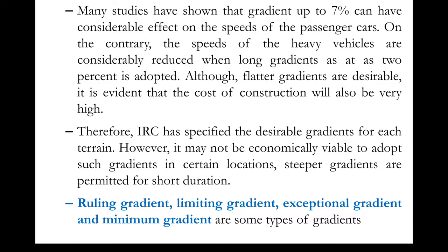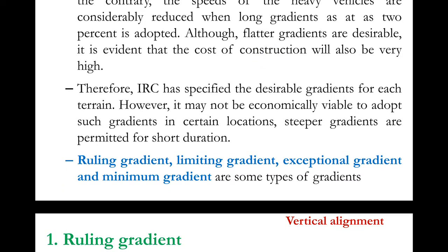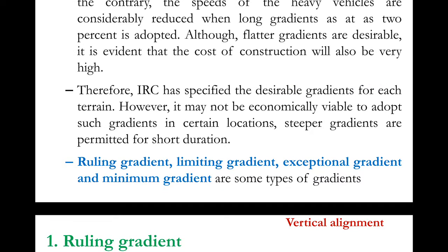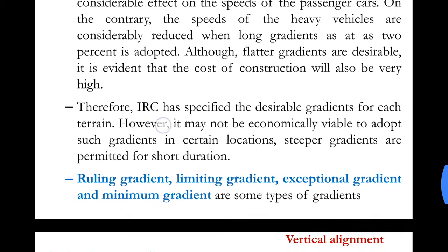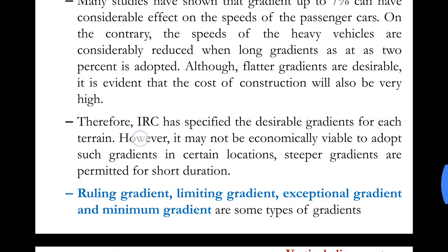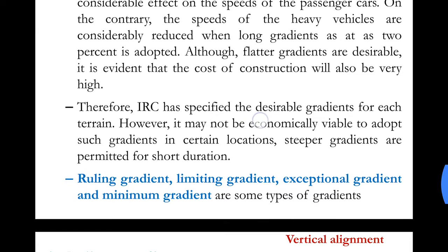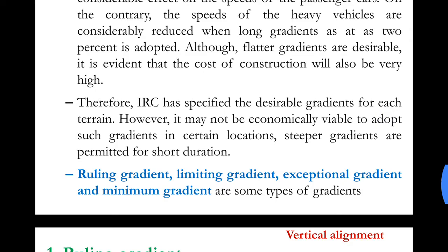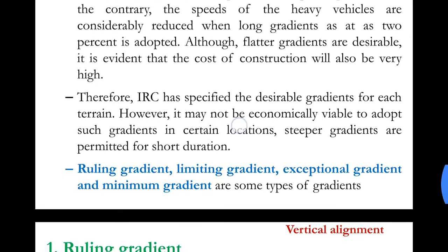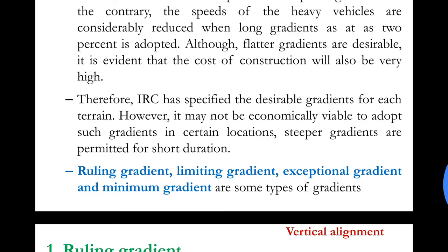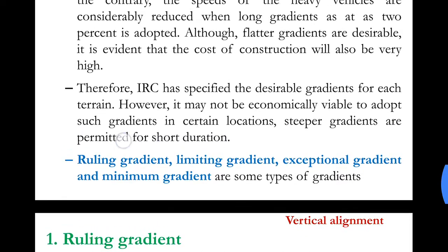Therefore IRC has specified desirable gradients for each terrain. For each type of terrain we have given a set of gradients. Out of these gradients we select whichever is suitable for that type of terrain. However, it might not be economically viable to adopt such gradients in certain locations. Steeper gradients are permitted for short duration.